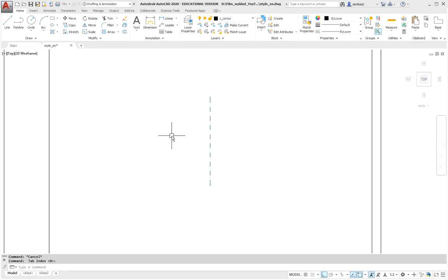If we have an axis drawn, we will enter values using the circle and diameter. Why so? Because there is the least probability of a mistake when entering numbers. Here we introduce that the center of the circle is at the end of the axis. After that the diameter is 29.8, because we will need the distance to draw in the upper part of the outline.